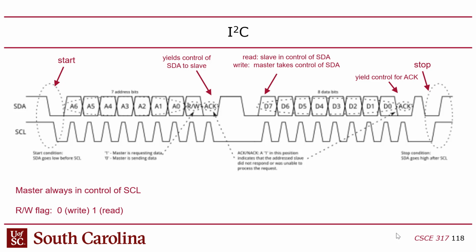So the effective voltage is going to be very close to VDD. You're going to get some losses over that pull-up resistor, but if it's a 5-volt system, it's going to be 4.9 volts, something like that. So it's going to look high. They're both high. No one's talking.